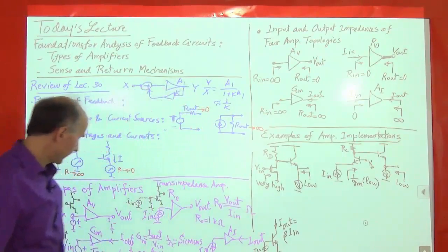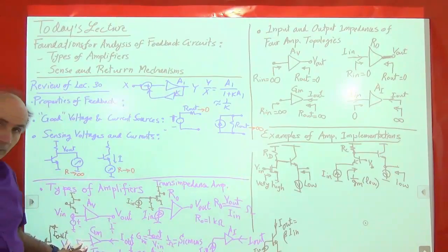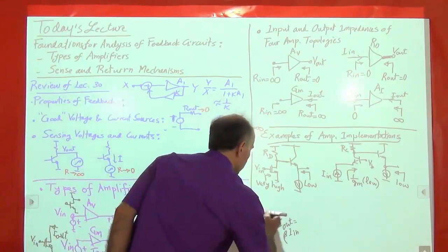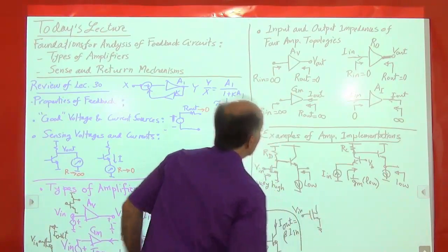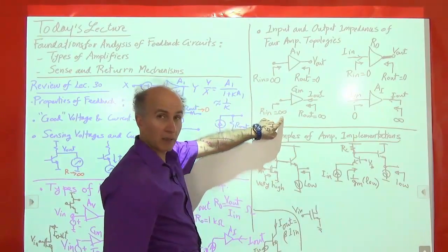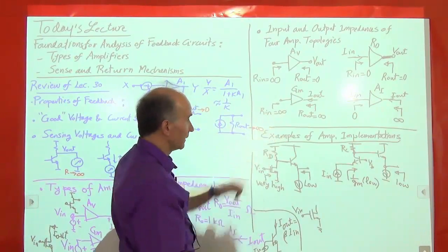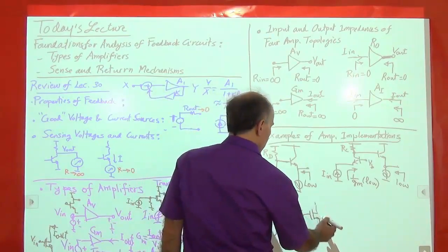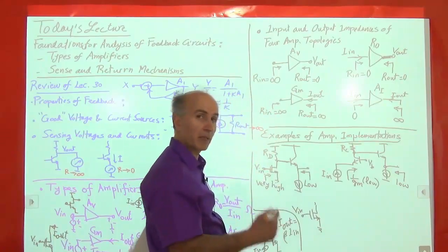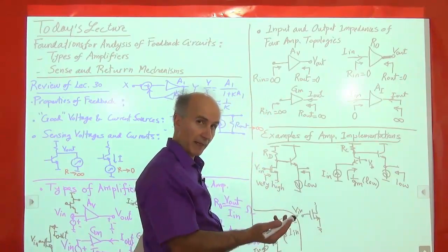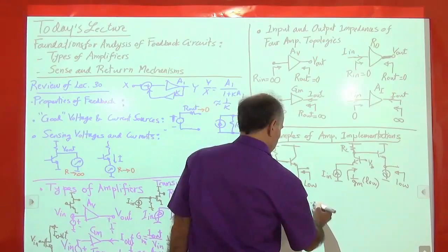All right, how about the transconductance amplifier? Well, we said that a single MOS transistor can do the job. So here's a single MOS transistor sensing a voltage. We are trying to sense a voltage with a high input impedance. That's great, we can do that. But then this output impedance is not that high, right? This is RO. Can I make it higher? Sure, I can make it cascode, right? So I put a cascode on top of this,